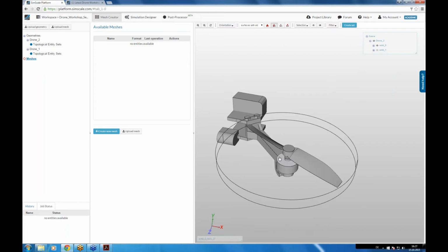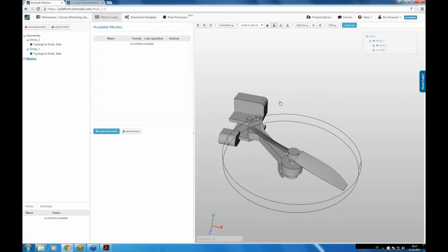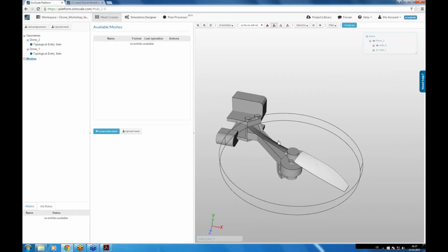You can really compare it to a digital image. It's like simulation pixels in three dimensions. Where you don't expect a lot of changes, like far away outside, you can use coarser, bigger pixels. Near the propeller, for example, we will have a lot of changes in the flow field, so there we need a finer mesh, finer pixels, let's say.